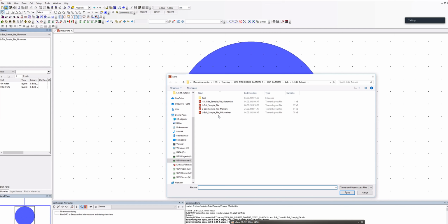Keep the layers that are visible, such as metal 1, metal 2, metal 3, and so on, right? The reason we're using different layers, we're going to come back to later as well. But in a complex design, you maybe want to have one layer as a base layer of metal, and then you have a mask with a different layer, which will be the second mask, for instance. So you don't mix these masks together. One mask has one layer, the second mask has a second layer, and the third a third layer, and so on. You can have designs that have 15 layers, right?